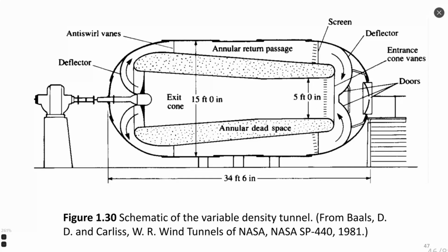And in order to reduce complexity of aerodynamic tests, not to have the same Mach and Reynolds kept in the test section, it is possible to test separately with different values of Mach number and to test separately with different values of Reynolds number, keeping just one parameter constant.